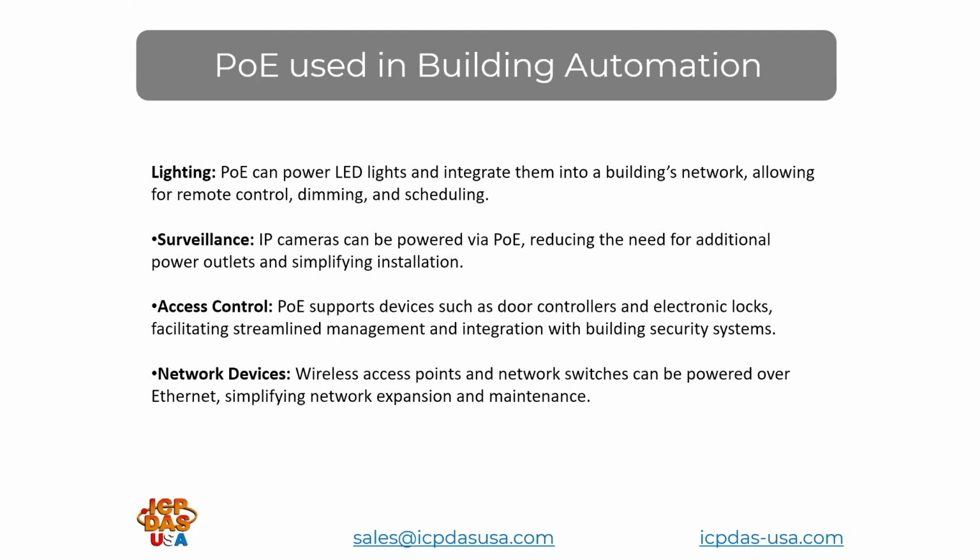IP cameras are oftentimes PoE powered. By doing this, you definitely make it much easier to simply connect a camera to a wired Ethernet connection. This greatly reduces the amount of wiring and simplifies the installation because the Ethernet connection to the camera can also carry the video.